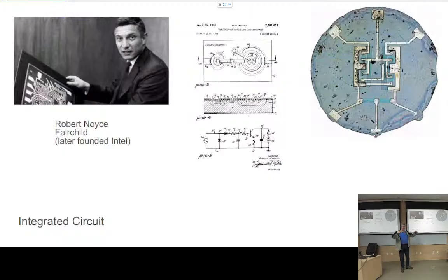So after he makes the transistors using the planar process that they were already using, then he added a layer of aluminum, just like you have a layer of copper in the printed circuit board, and did the same thing so that you'd have only the tracks. And these weird squares around the corner is where you'd solder a tiny little gold wire into the pins, right? So this was, and this is, the first commercial integrated circuit.